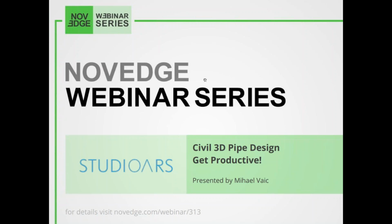In this webinar, we will focus on the top 5 ways to boost your Civil 3D pipe designs with Urbano Visio. Number 1, set a uniform pipe invert flow for multiple pipes. Number 2, set a uniform structure sump depth for multiple structures. Number 3, change the pipe diameter for multiple pipes. And number 4, calculate trench volume estimates. And finally, create data-rich IFC models.